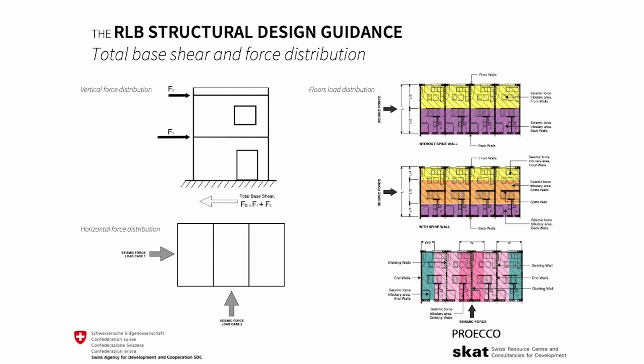This method is reliant on several assumptions, among which floors being flexible diaphragms. A flexible diaphragm can be considered as a simply supported beam spanning between two stability elements. Loads are distributed based on tributary widths, with half of each span going to one support and the other half to another.